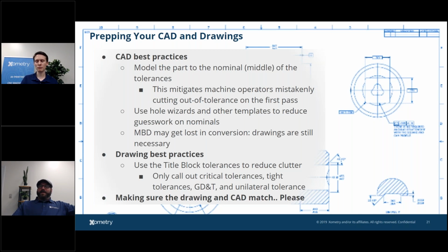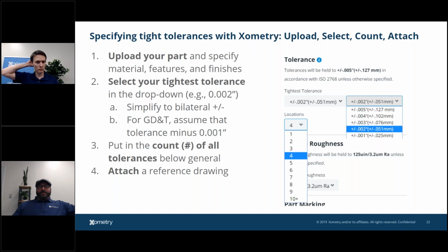Yeah, the other thing is, if you're designing a print and you're finding that your dimensional features are overlapping each other, it's very hard for a QC to figure out what line goes where. And so it makes it more difficult. So use that tolerance block as much as possible, and use multiple pages on your drawings if you have to. Don't try to cram everything into one page. It doesn't hurt anything in a PDF to just pull up page 2.